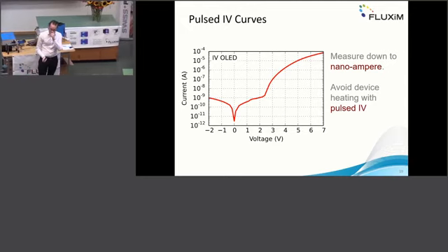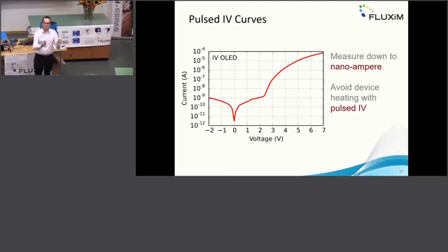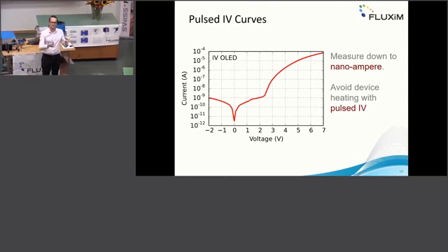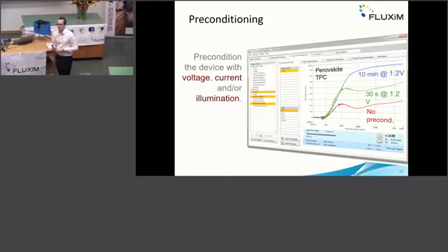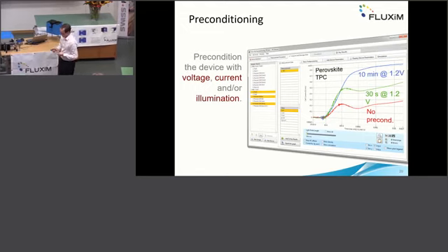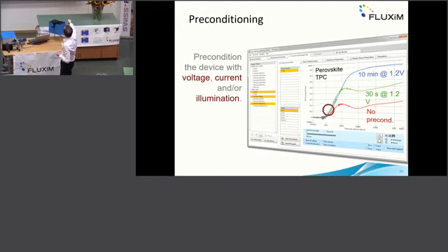For perovskite solar cells, what you often see in publications, especially in the ones from Brian O'Regan and Philip Calado, what they often do is they name it tabbing. We call it preconditioning. It means we first apply a certain voltage to a perovskite cell for, let's say, a minute, or a light intensity, whatever, for a certain time to precondition the ions, and then quickly after we do an experiment. And this looks like this. So, for example, this is the transient photocurrent onset of a perovskite solar cell, where you see without preconditioning, it looks like the red curve here, and the longer you precondition, the faster the current rise is.